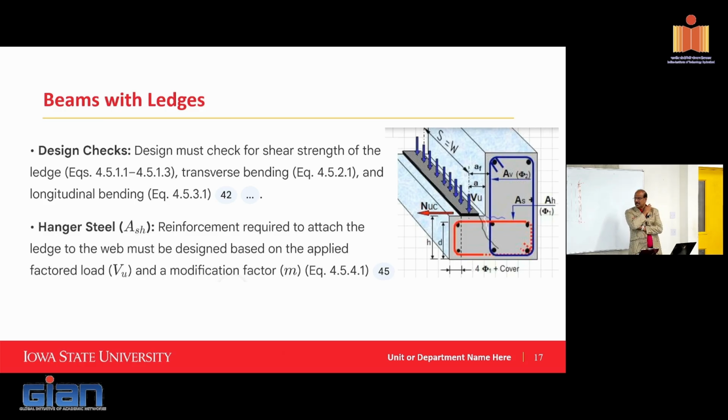I think my next slide is actually about the bearing pad. The second thing is that they avoid stress concentration, especially if you have a dapped end. When it sits, if you have stress concentration, you could cause localized failure. So it's a requirement that they put in bearing pads on those locations.